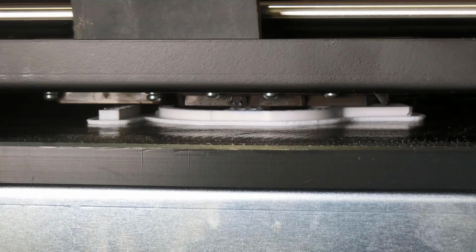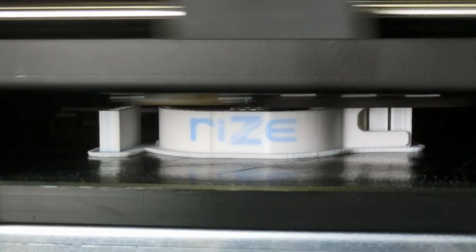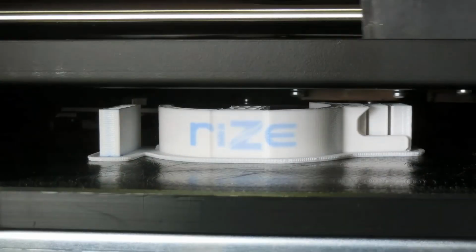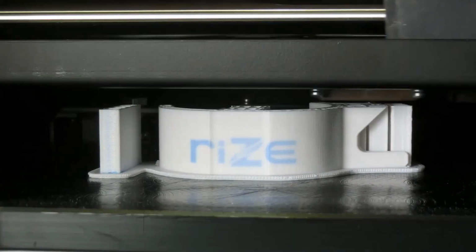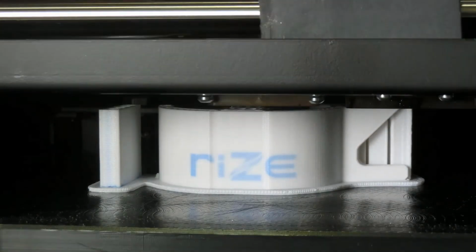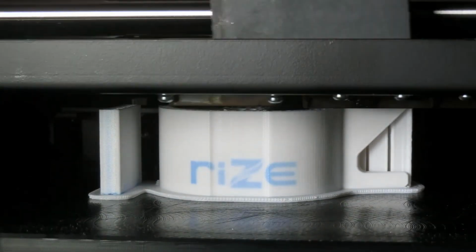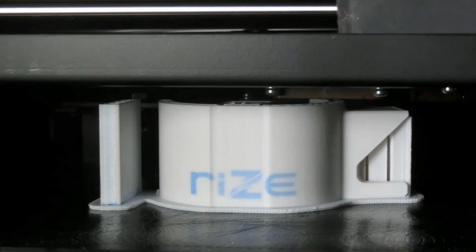Also, along with this filament, we have this process called APD, which actually puts release ink and marking ink. What this release ink allows you to do is very easily remove the supports. Everywhere there is a support touching the part, we put a layer of the release ink, and once it comes out of the machine, you can very quickly peel away the supports, and you're all set.